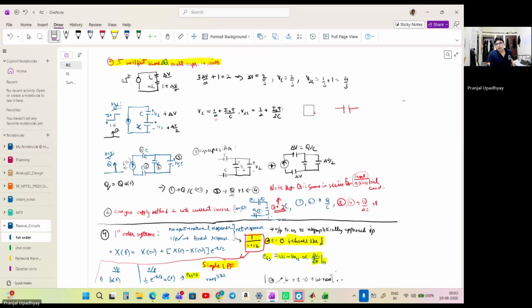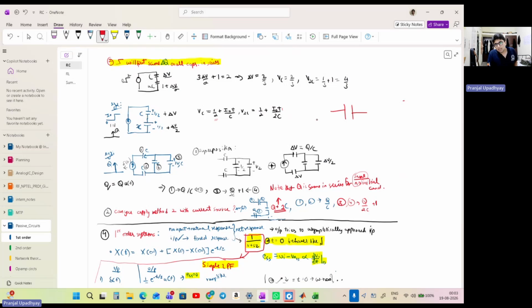So the idea here is that when I'm feeding a current source, it is constantly trying to inject charge into the capacitor, right? It is constantly trying to put some charge over here, and here also some minus Q charge will appear because of the pull by these Q charges accumulating here. And this is just happening and happening because the current source will keep pumping the charge over here. So the capacitor won't reach any steady state at all to begin with, because the current source keeps on pumping the charge on the capacitor plate.